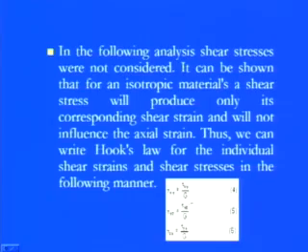As far as the axial strains or the normal strains are concerned, the modulus of property was the Young's modulus. But here, since we are talking about the shearing of a plane, due to the shear stress present the shear strains are there, which means this Young's modulus is not valid. Then we need to define a new modulus, the shear modulus of elasticity, denoted by G.